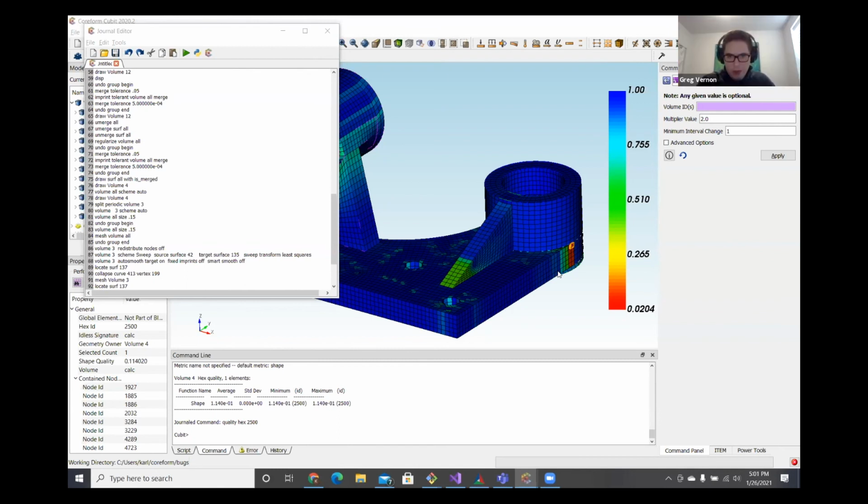Yeah. So this one about local mesh refinement. We're actually developing sizing sources that will allow you, for say TET meshes, to define regions of local refinement. But that's also a good area to use the Python API to define where to put small elements, because you can query the geometry and stuff like that. So that's another area that might actually be the topic of a future Python webinar.